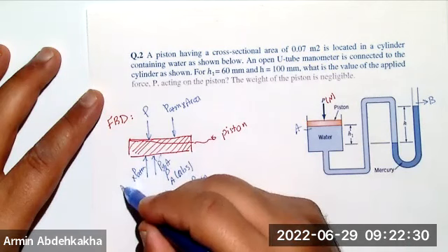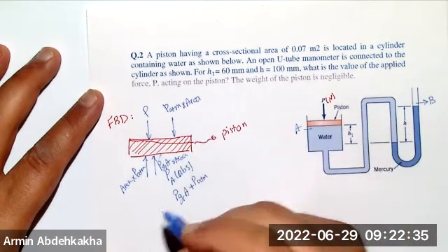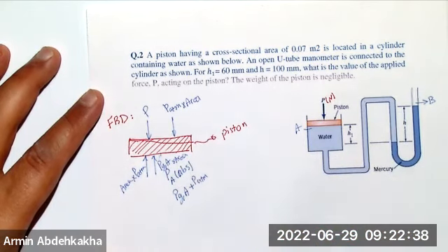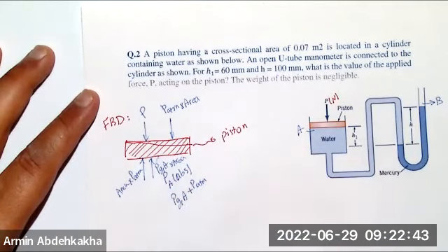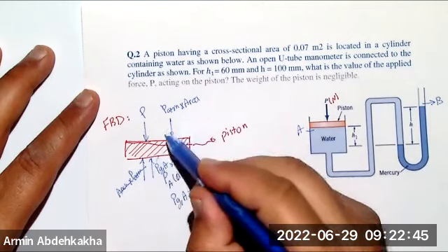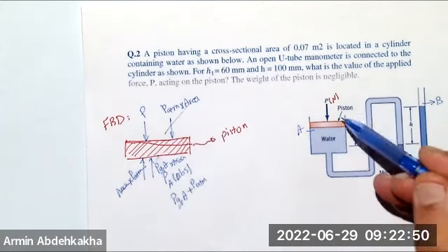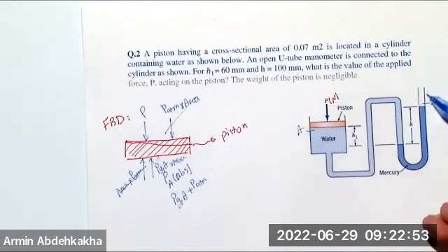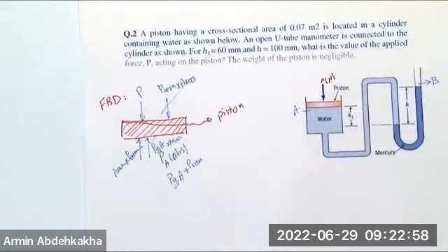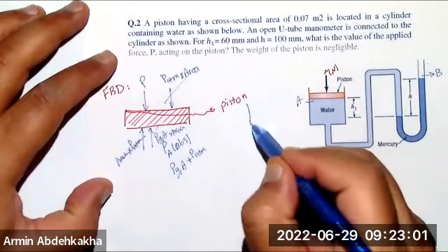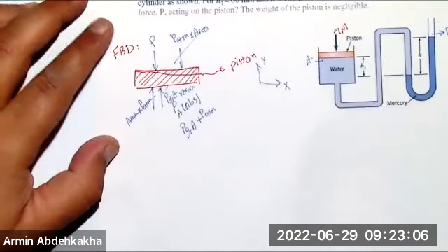So both of them should be multiplied by the area, correct? If you multiply those by area, then you see that these two forces are going to cancel each other out, because the atmospheric pressure that you have on top, you will have here too. Then these two are going to be canceled, right? With this part, again, you need to show your directions and your reference points.